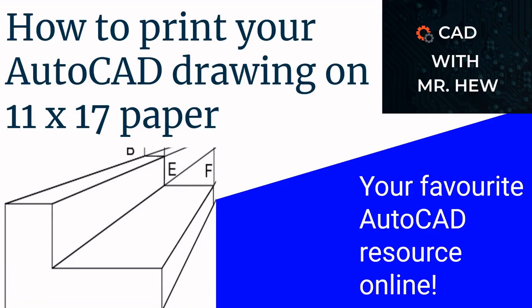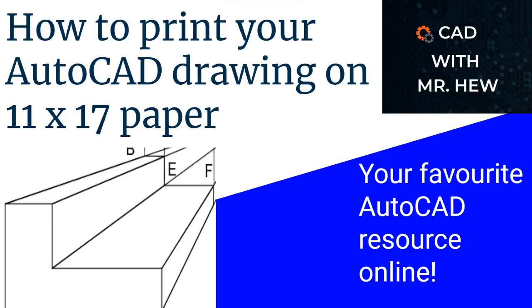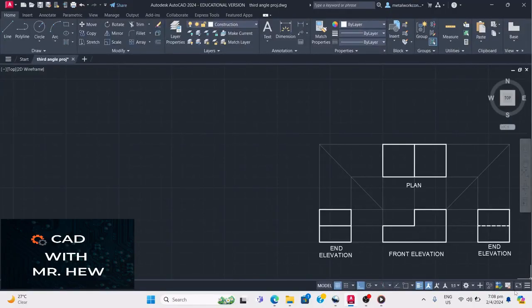In today's video, we're looking at how do we print our AutoCAD drawing on 17 by 11 paper, which is also known as the tabloid paper. Now, in the previous video, we drew a third angle projection drawing, and in today's video, we will be printing this drawing on the 17 by 11 paper. In today's video, we'll be printing in model space. So here we have the drawing which we completed in the previous video.